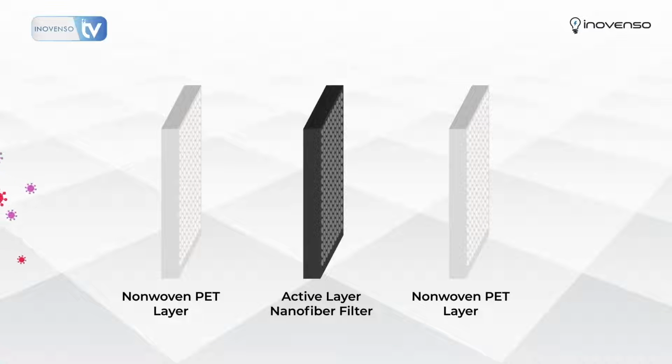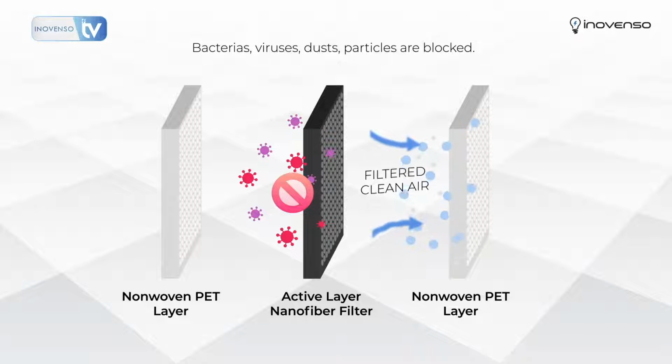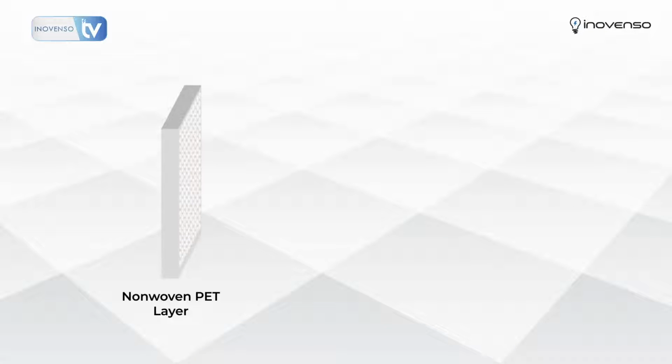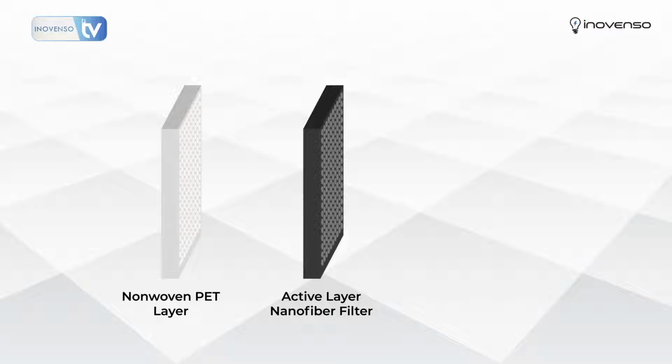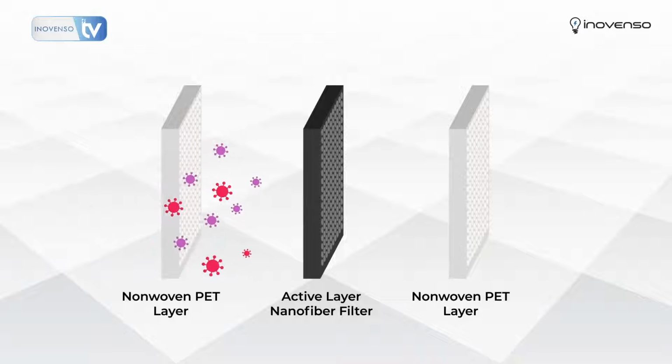So I want the substrate to be moving from left to right, and at the end of the roll, it should be a roll full of nanofiber filter media on PET substrate. While that's rolling, we also want the nanofiber electrospinning jets to equally distribute onto the polyethylene terephthalate substrate. So I'm going to activate the homogeneity option also in our machine.